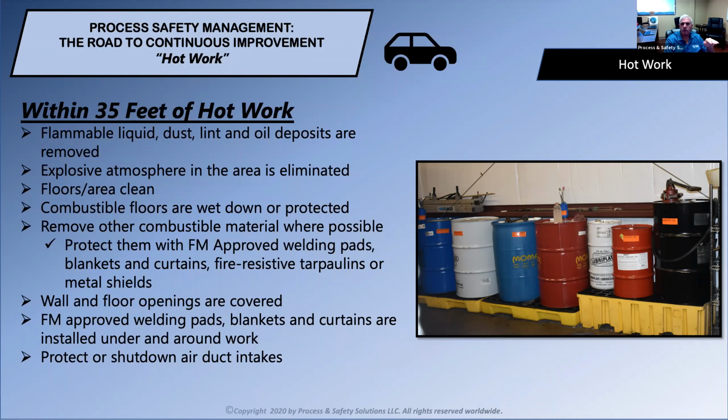This really goes to monitoring the ambient conditions in the hot work area and within 35 feet of it. Make sure the floors in the area are clean, that you don't have dirty, oily rags laying around, and that you don't have containment pallets with oil in them right next to the hot work area.